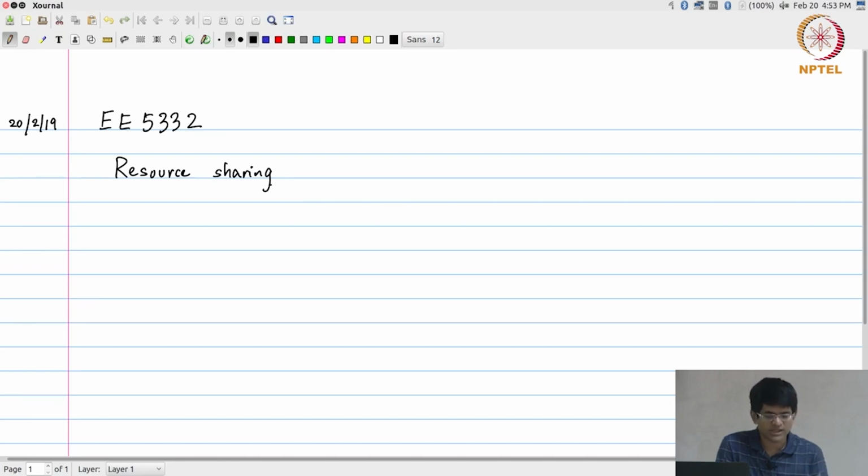Resource sharing on the other hand is looking at the opposite end of the problem, right? It's saying, let's assume that I can run fast enough, I do not need more throughput at this point, but I do have a problem with using up too many resources. I do not have the amount of hardware that is required to implement a completely parallel implementation or a fully dedicated architecture where each actor has a hardware unit associated with it.